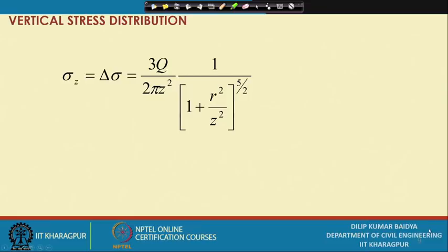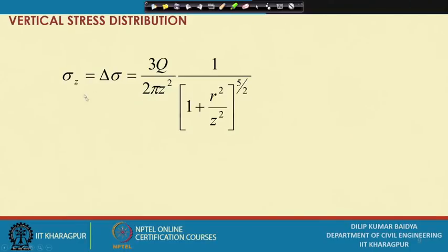In soil mechanics, subsequently we will see many areas where you have to first calculate the sigma z component. The force is applied at a surface, and then at a particular depth we obtain the value of sigma z, and that finally has to be used for some other calculation. Because that is frequently used, we will show this application subsequently. So, I am concentrating more on sigma z.